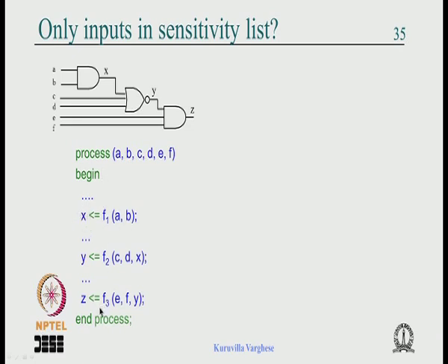Once it is completed there is nothing more to do at 100 nanoseconds, so the simulation time goes to 100 plus delta. So if X is specified, this is computed again and Y gets updated. Now in the next iteration there is a 100 plus 2 delta event, and if Y is there it will trigger and Z is updated.